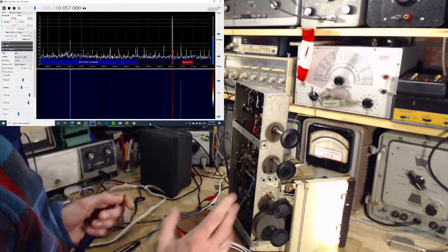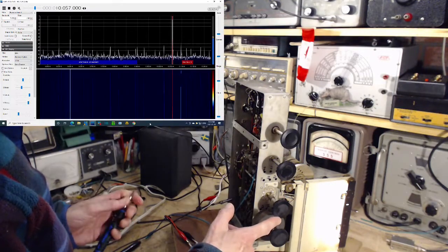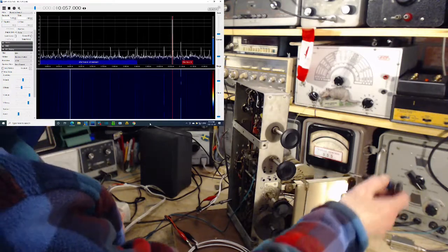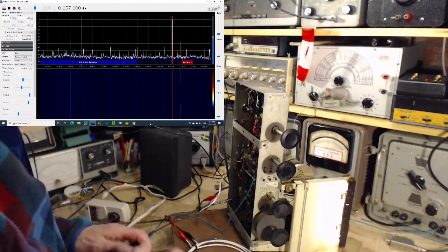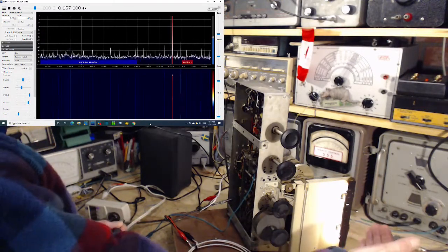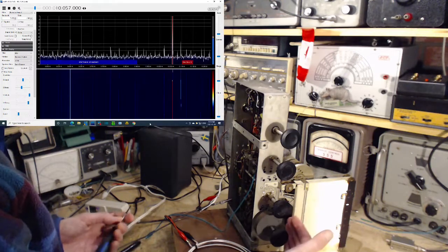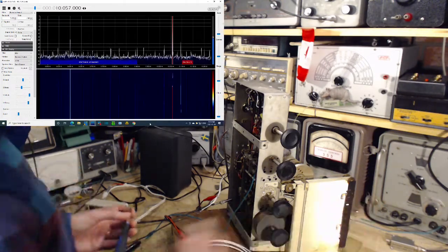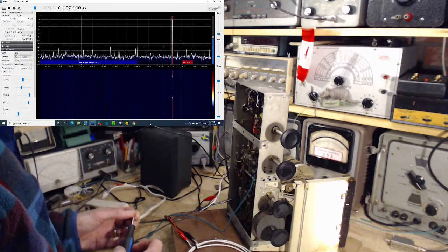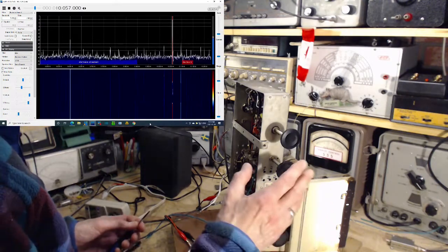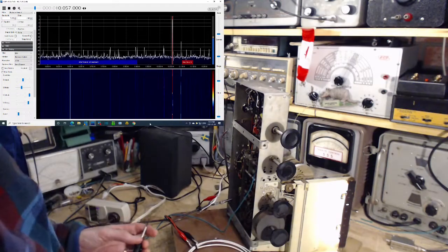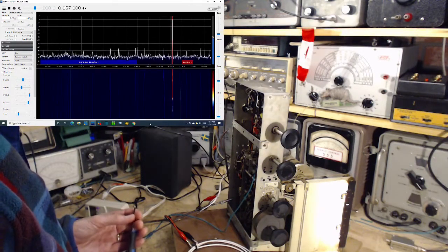When I did the first 6 megahertz adjustment, I should have marked the location of the bar here. I could just mark it on the side somewhere, so I can return it to that exact physical position, and then re-correct the oscillator at the low end after having adjusted the high end, because adjusting the high end probably moved the low end. And because this particular band involves adjusting the capacitor, like the tuning capacitor, the adjustment of this band affects all the rest. So I really need to get this right.